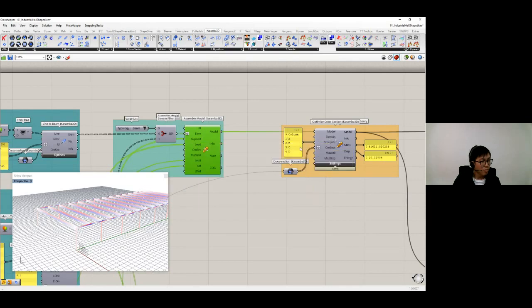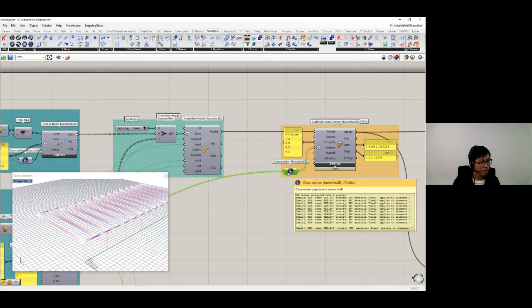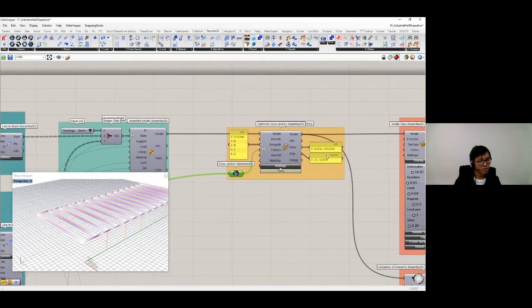In our setup, I'm optimizing all of the members, but basically using them as a group optimization. So I'm using all these element IDs that I've specified here, meaning that all our beams A1 and A2, which have been set in a group element set A, will be optimized as one profile, as you see in our render view right now. This is the list of 24 HA profiles that we have. And then we already see the results from the optimization, the mass and the maximum displacement of this setup.